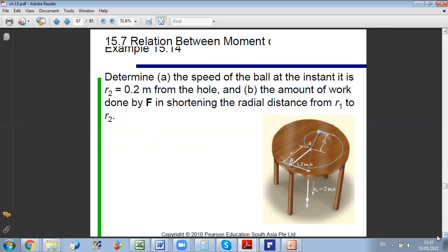And you should have used that it is a central force. They told you it's a central force motion and helped you further, telling you to find the constant of area. Since you want h, which is constant, once you get h you can get theta dot at any position, because h is r squared theta dot.